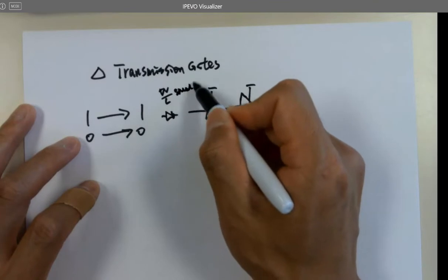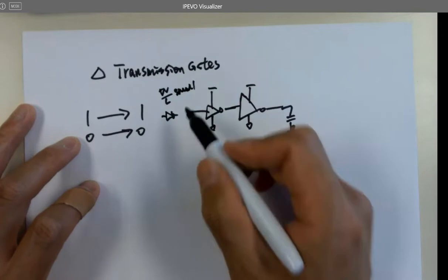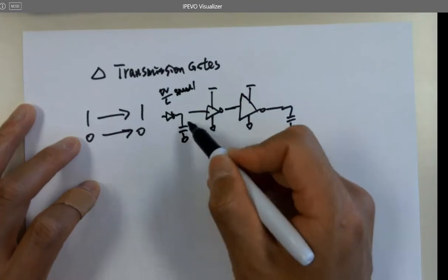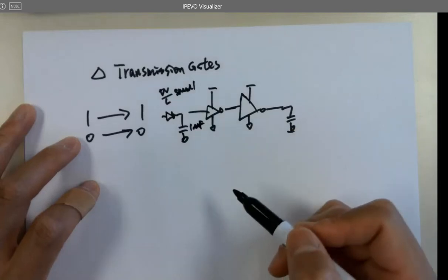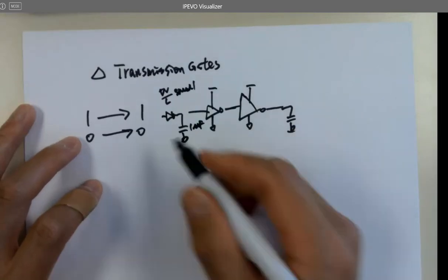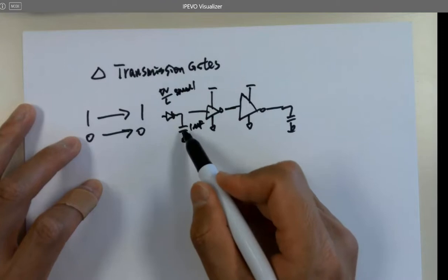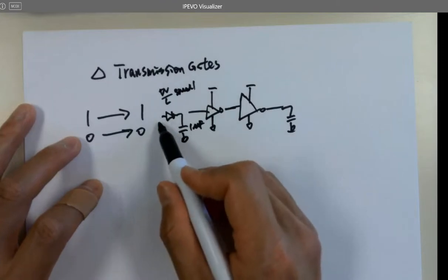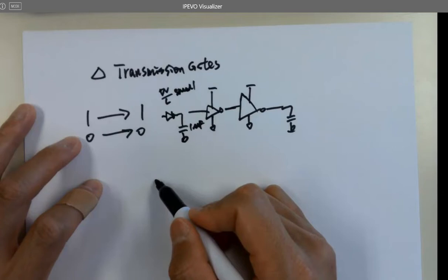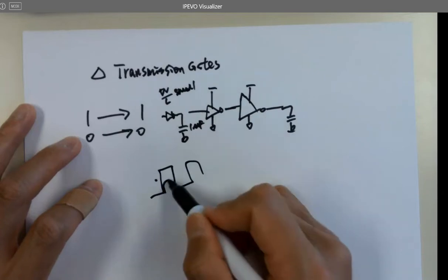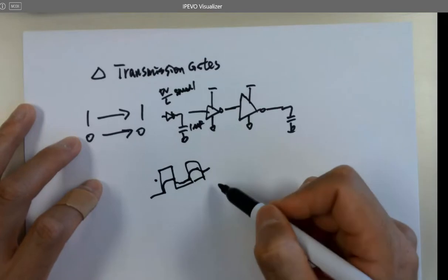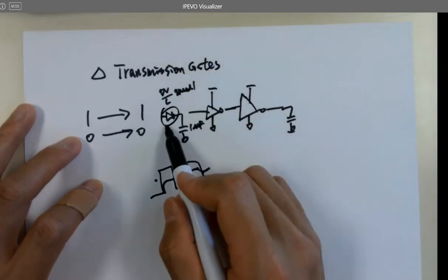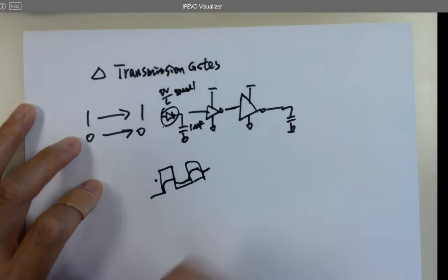So you have a small inverter, then you have a huge cap, like 1 microfarad or larger. And you won't be able to charge and discharge this efficiently if you have a pretty fast pulse. You know what I mean? It's going to do this, because this inverter does not have the driving capability to drive that huge cap at that speed.